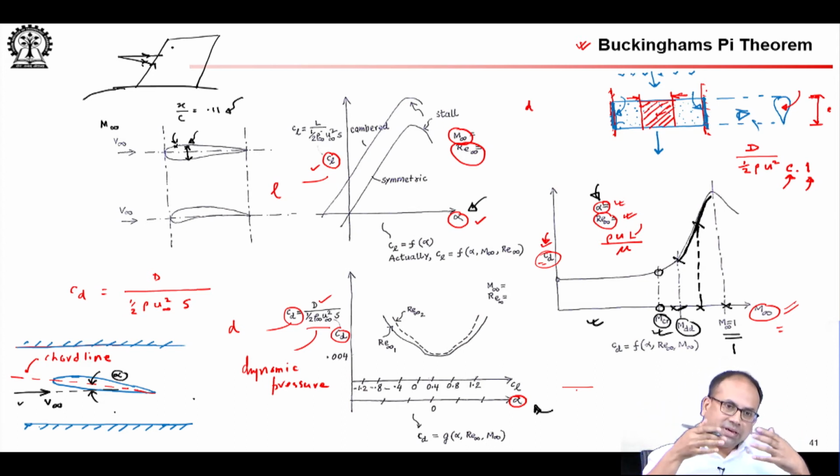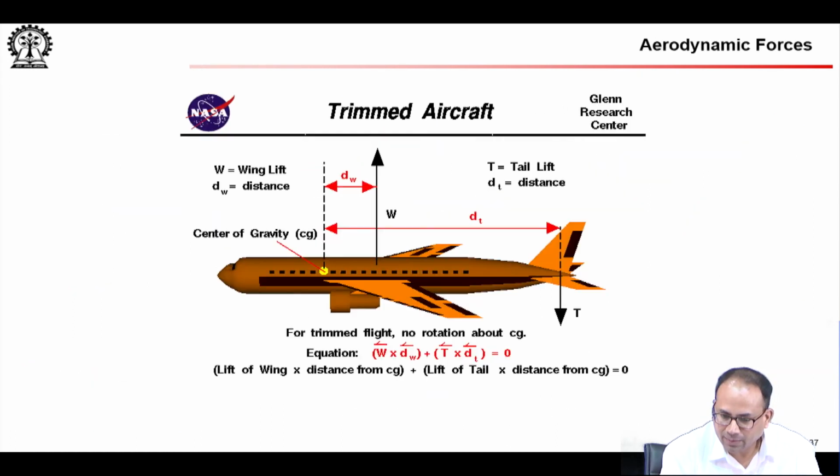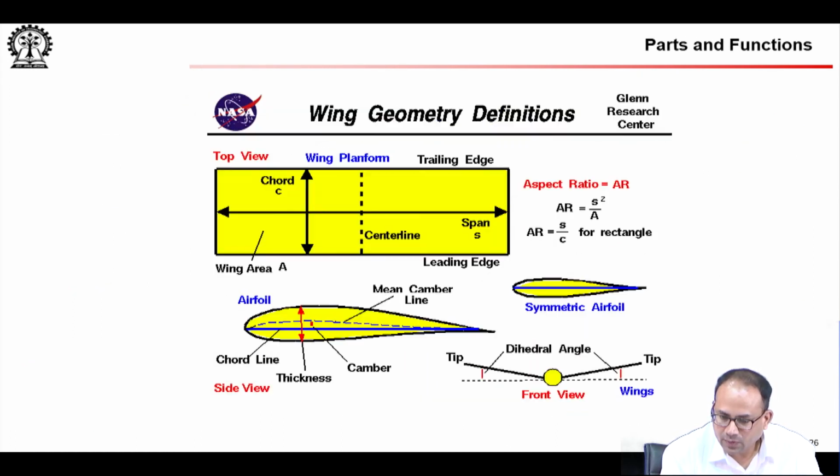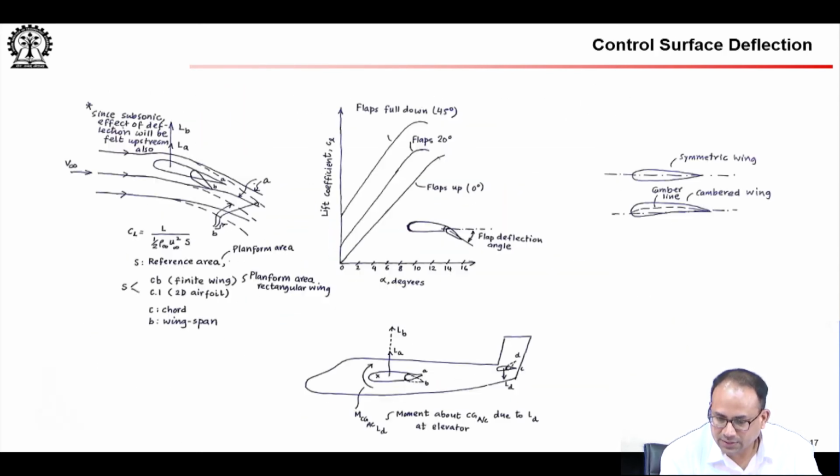So, the leading edge, although the vehicle is flying at a certain Mach number, say the vehicle is flying at this Mach number here on the lower right, your wing will see something like this. So, the component that is normal to the wing. So, sweeping back has this advantage that your vehicle can still fly at high Mach number, but the wing will not get into that high drag divergence situation.